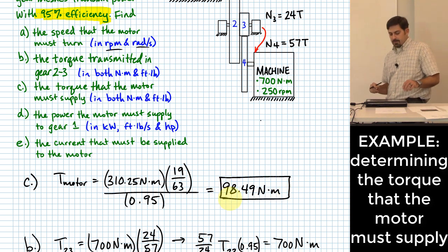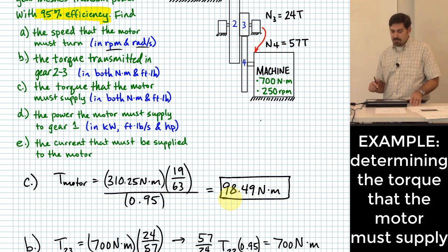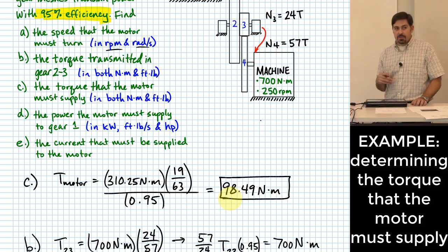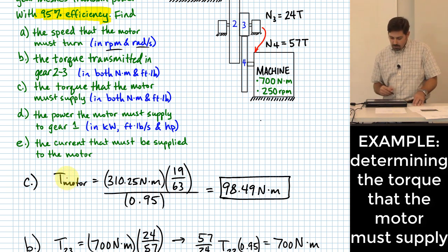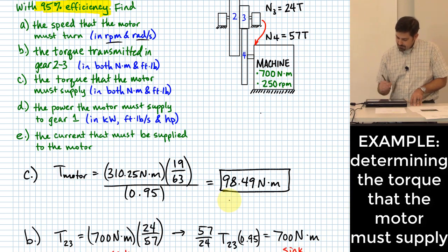Ooh, yeah, we're going to get to that. His question was, what about the motor being 70% efficient? That's the motor's efficiency at turning electricity into torque, turning electricity into the power that's coming out of the shaft, basically, right? And so we will need to deal with that, but we're not quite there yet because what we've done now is just figured out how much torque needs to come out of the shaft, right? And here it is. What is this going to be in foot-pounds?